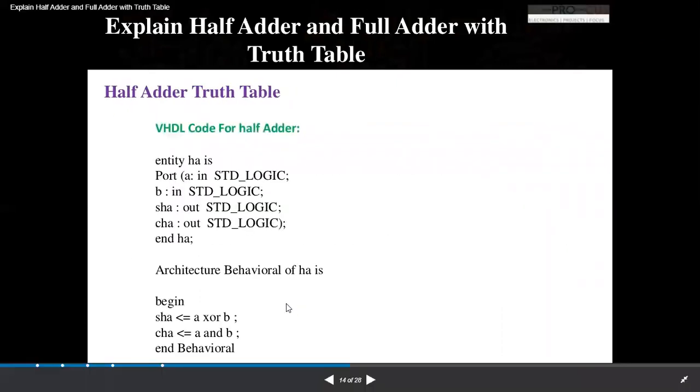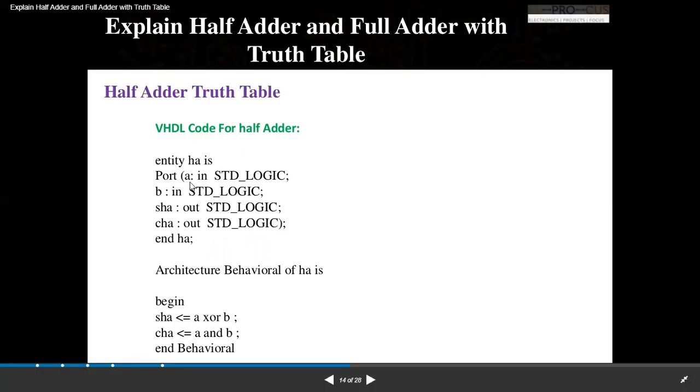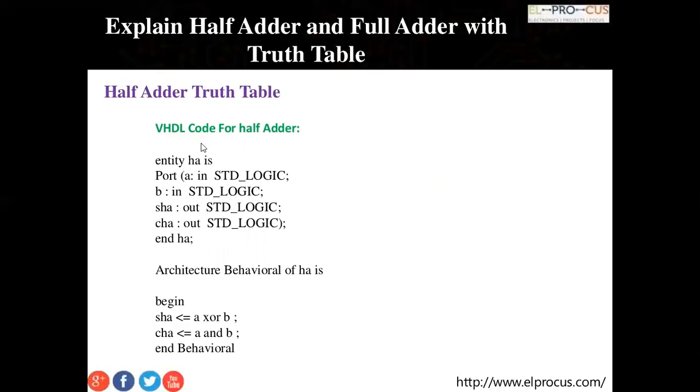After the half adder and full adder, we know how to design a code for the half adder with its truth table. Here, firstly, we define the entity and architecture, and we call the libraries. Sometimes the libraries are not written, but we have to write them down. The library declaration we already know, and we are using the IEEE library.